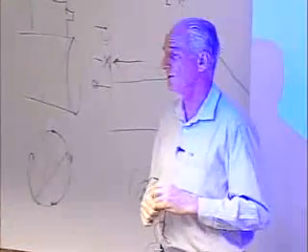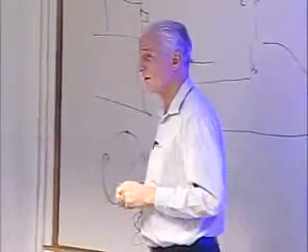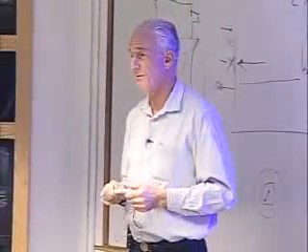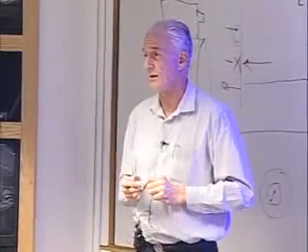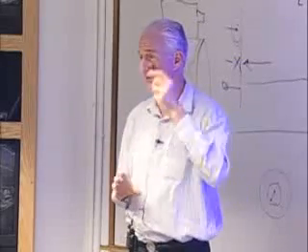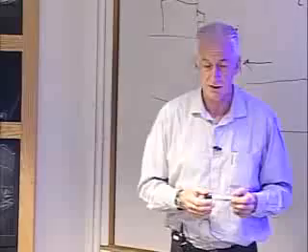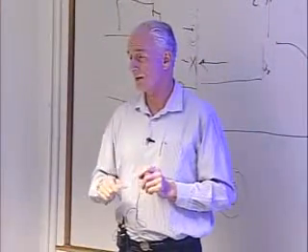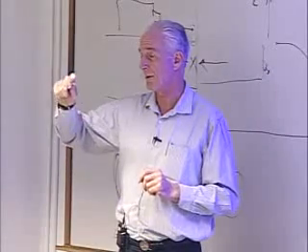MECO is different. The same thing happens. The main engines are working at maximum, 104% thrust. We don't take them up to the 109, which is emergency only. They're working at 104% thrust, and your acceleration now starts to pick up.